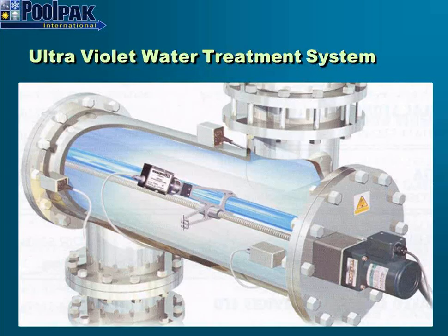That device that you see on the bulb is sort of like a little carriage that goes back and forth and cleans that tube if necessary. There's a sensor on there that senses how much light is coming off the UV bulb. If it decreases, then the carriage moves back and forth to scrub deposits off that bulb and restore the system to a better operating condition.